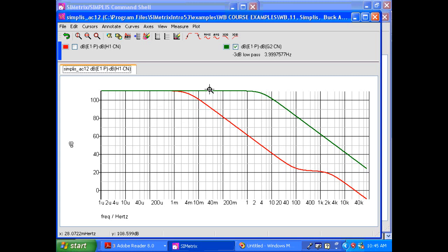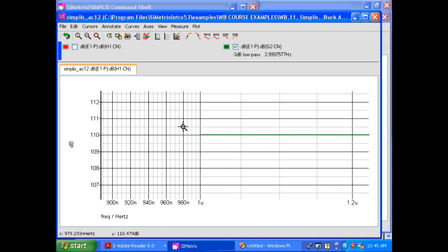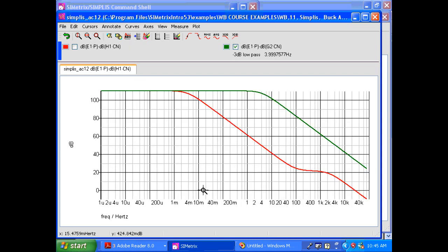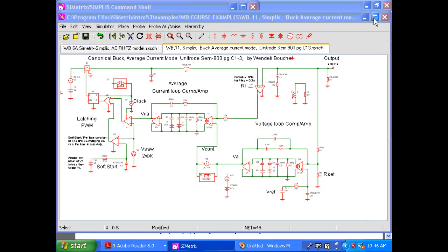And you can see that this is the open loop amplifier gain. It's 110 dB, and if we do that, we can see it. 110 dB right here. And this is a minus 1 slope. And again, we say if this curve ever comes close to this one within 5 dB or closer, then this one will control this curve. And we don't want to do that, of course.